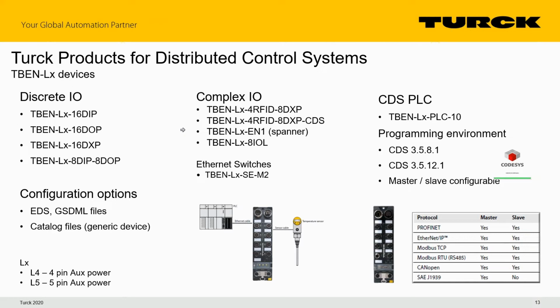PLC B reads that data table. PLC B writes to a different table. PLC A reads from that second table. So the two are able to communicate data up to 480 bytes without either PLC being forced to do that protocol transition in the PLC.